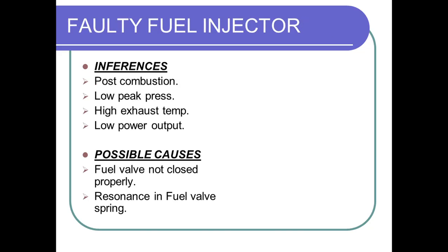Now, faulty fuel injector. The inferences are post combustion, low peak pressure, high exhaust temperature, low power output. What are the possible causes? Fuel valve not closed properly, and resonance in the fuel valve spring.